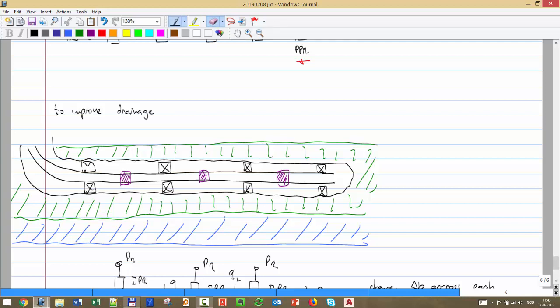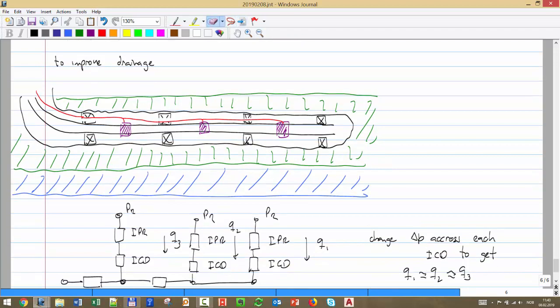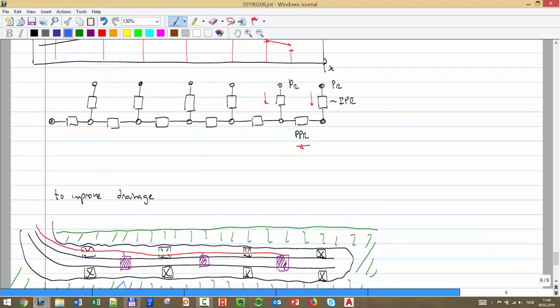I have to pull a line, I have to put a hydraulic line through here to enter into this one, and then I have to put one going to this guy, and then one going to this guy, depending how many I have, to be able to regulate this choke. I want more choking, less choking, and how that's going to change. For example, if I know that in one of them I'm going to get water breakthrough in the life, then I have to close it. And that, if I want to have that option, that's going to add cost.